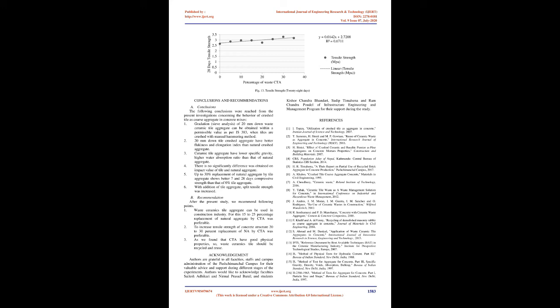Design mix of concrete. The mix design in accordance with the Indian standard was done for the concrete mixing for M25 grade. With increase of tile percentage, cement quantity also increased. That means the cement to aggregate ratio increased. With a higher percentage of CTA, water required for the mix is also high. That indicates that with increase of CTA in concrete, the amount of cement and water also increased. The increase in W/C ratio was due to the high water absorption value of CTA.